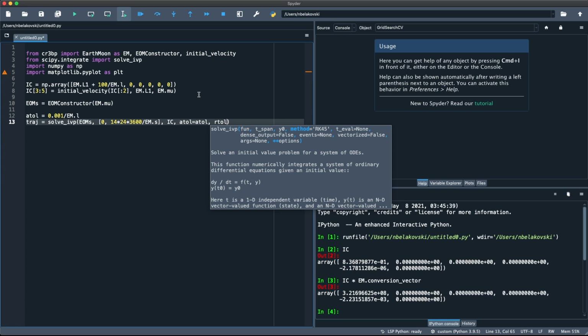RTOL is relative precision, so that's like number of significant digits, and I don't really prefer that one because I want to know that everything's millimeter level accuracy. With significant figures, it's a little awkward because our x position is kind of large. In non-dimensional terms it's only one more significant digit, but I'd rather think in terms of millimeter level precision for everything, instead of trying to think about which value this term is going to have and how many significant figures.